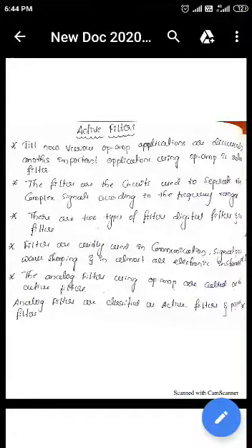Of operational amplifiers such as inverting configurations, non-inverting configurations, addition, subtraction, multiplication, division, summing amplifier, peaking amplifiers, various types of amplifiers we have studied. So now in this particular second module, it is all about the filters. So first let me discuss what exactly a filter is. A filter is nothing but an electronic circuit which separates the complex signals as per their frequency range.